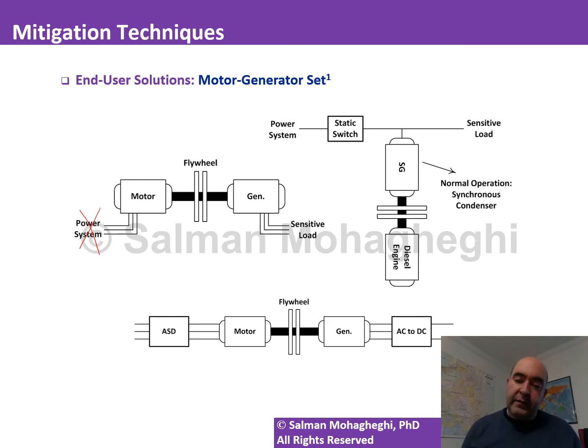There are a variety of different configurations for this. So this would be similar to what we talked about on the previous slide. This would be like the online scheme. In addition to that, you can have more like a hybrid scheme or standby scheme, whereas this is not providing the power at all times. Under normal operating condition, it could be operating as a synchronous condenser, and then if anything happens, it can start injecting active power.